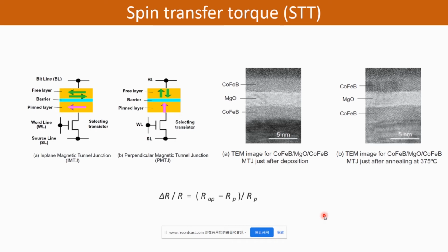After annealing with the magnetic field, the cobalt layer was crystallized in the 001 direction, as shown in picture B on the right side. The TMR ratio increased up to 350% after annealing, and this indicates that the formation of a highly oriented 001 sandwich structure is essential to obtain a high TMR ratio.